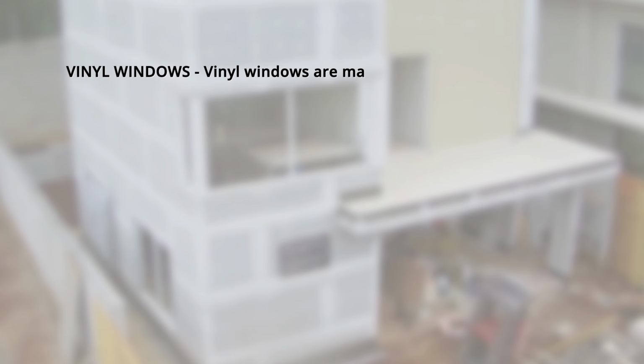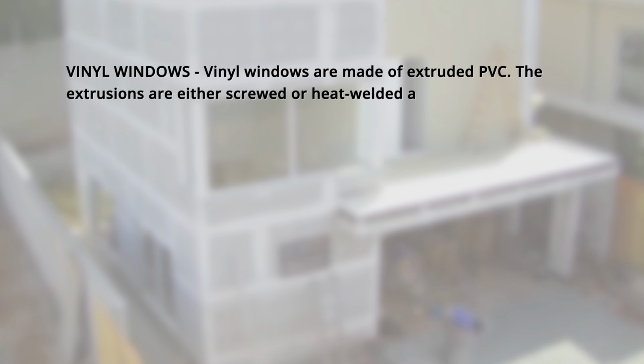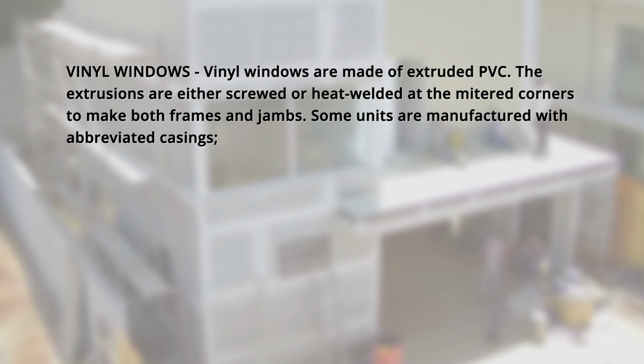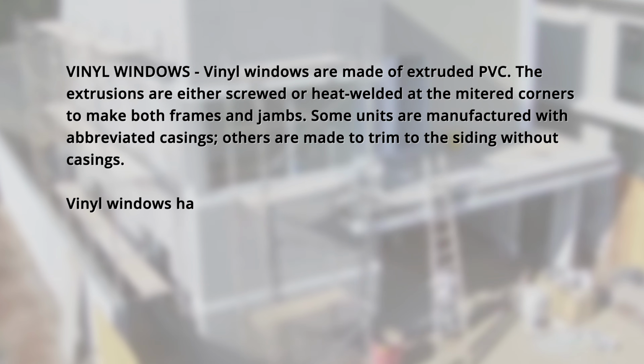Window materials. Vinyl windows. Vinyl windows are made of extruded PVC. The extrusions are either screwed or heat welded at the mitered corners to make both frames and jambs. Some units are manufactured with abbreviated casings, others are made to trim to the siding without casings.